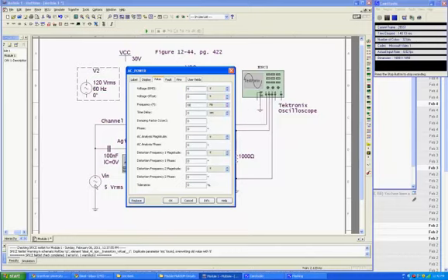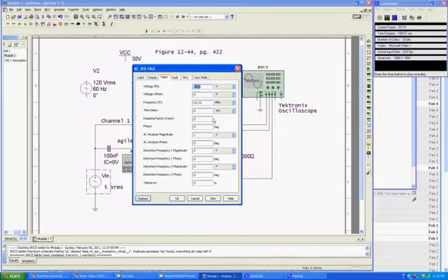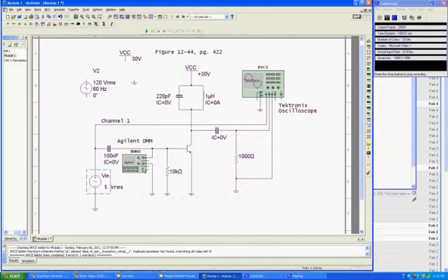Another thing while we're here is the phase. By default, we'll just leave that at 0. But I wanted to check what frequency I had set here. Looks like 10.73 megahertz. Okay, so that's basically all there is for your AC source.